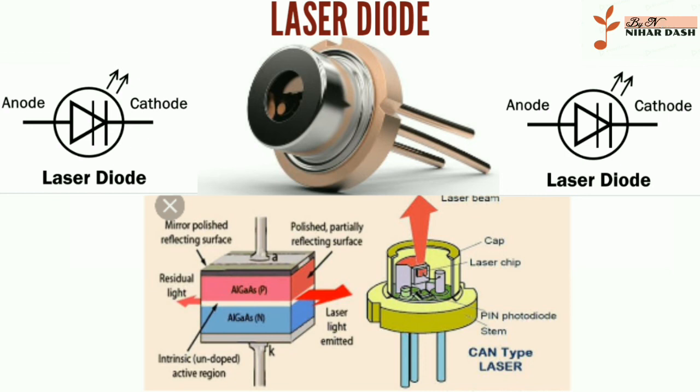Let us now understand the process of stimulated emission. Stimulated emission of laser diode. Suppose after absorption, the atom is present in the higher energy level, before the exhaustion of its lifespan. So, an electromagnetic wave of frequency equal to the frequency of the spontaneously emitted photon is provided to the atom. This causes the atom to perform a transition from E2 to E1. Now, this time the atom will release the energy of two photons in this transition.